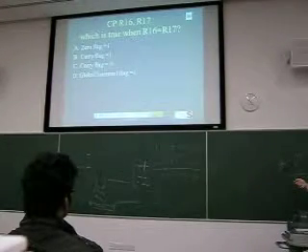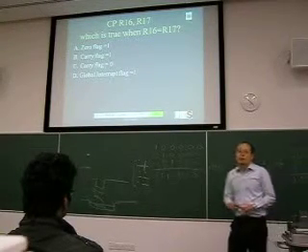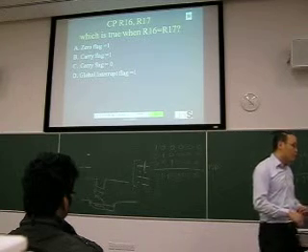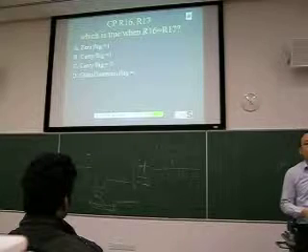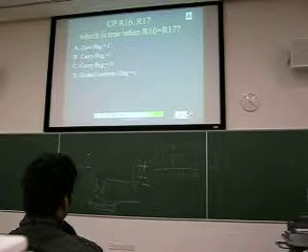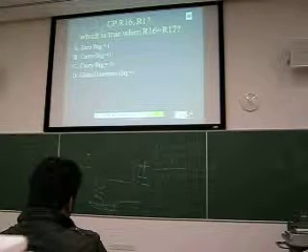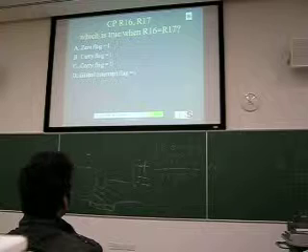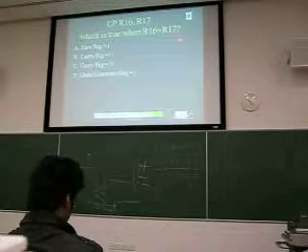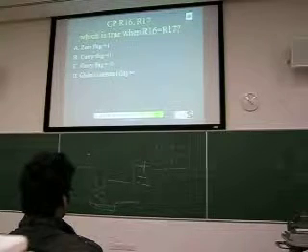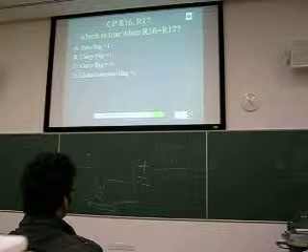But this one you have seen in lab 1, I think. But I want you to, this one is the most important, because you will have to know this to be able to understand the lab today. So what I'm doing is I'm comparing 2 registers. In this case it is R16 and R17. Okay? So let's say the value in R16 is the same as in R17. Which flag in my status register would be set or not set?